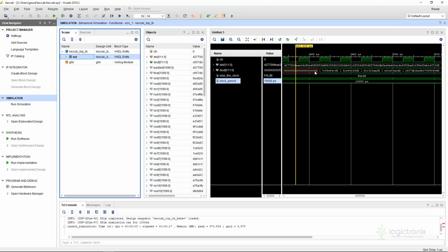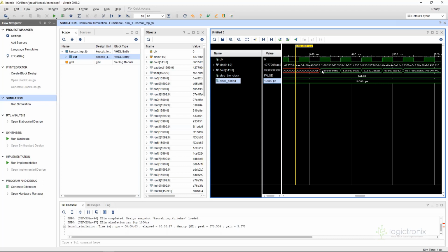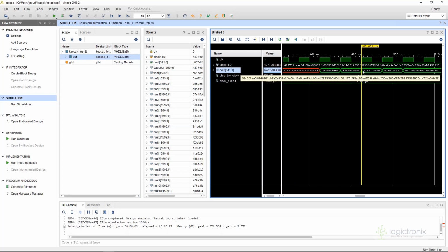If we calculate, we are getting every output at every clock cycle. That means we are getting a hash rate equal to the clock rate of VCU or some high-end boards. And as high-end boards can support up to 600, 700 megahertz, we are getting that. That's really great. One point is we are using only 4% of the resources with such an extreme hash rate.